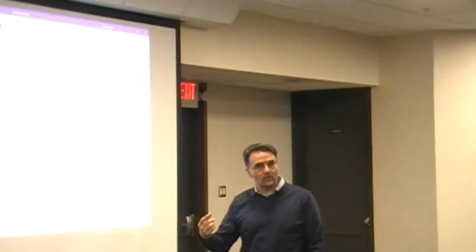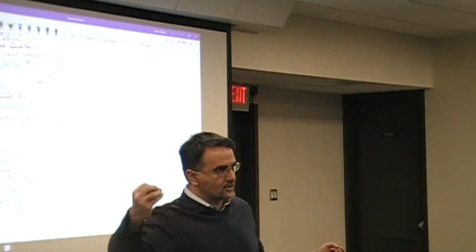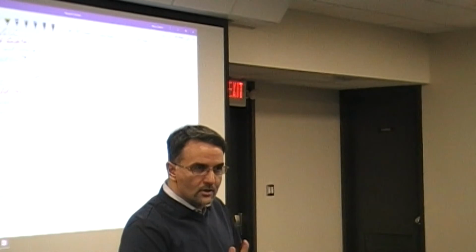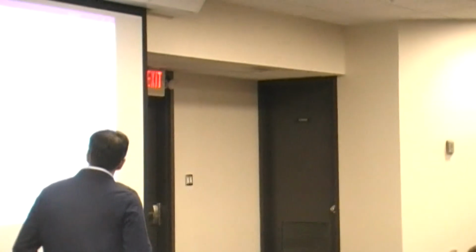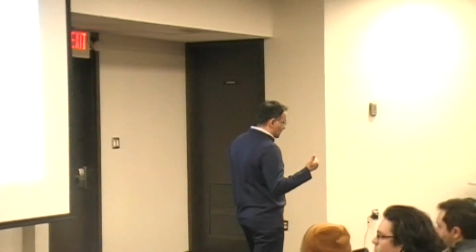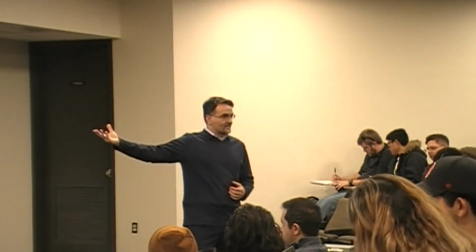Remember how you characterize permeability in general. Permeability has to do with the speed of the traveling water molecule within the soil medium. If you elongate the path of the seepage, you essentially see a lot of friction between the water molecule and the soil, and therefore you see more loss. So the permeability of your soil is going to be a whole lot lower. So well-graded material is great for foundations, great for providing a robust platform, and great for providing a relatively impermeable layer.